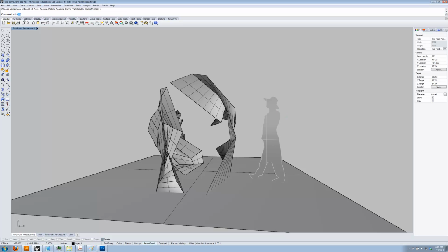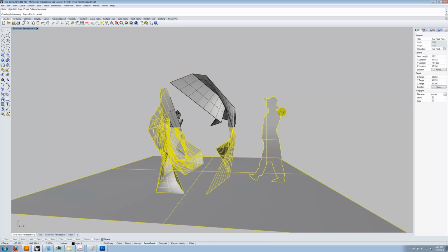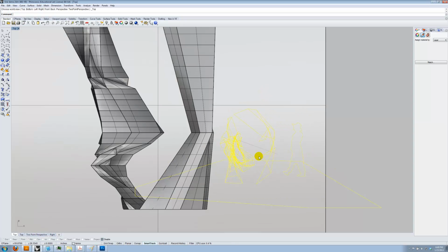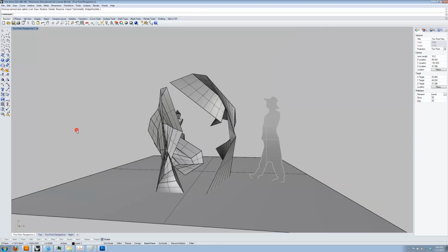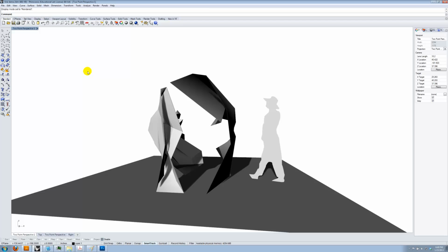So from here you can do all the stuff we just did, like Make 2D, select everything, right? It's going to take a little bit longer here. And then if I go to top view, I've got my lines. You probably want to ignore the ground lines for the most part. Then if you go back to that view, because we have the camera saved, you can do your rendered capture as well. So think about getting perspective views that are relevant into your presentation.